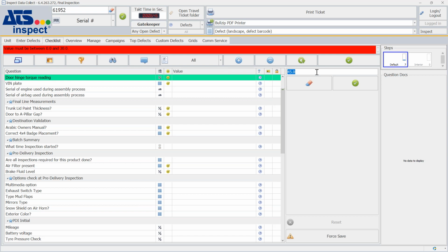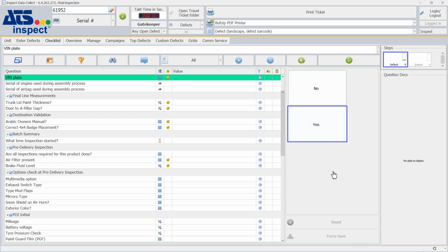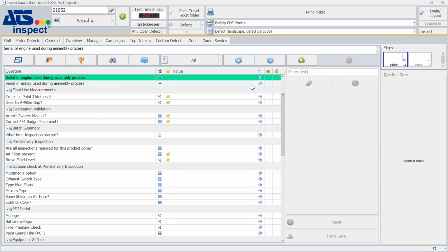And inside that reasonable limit, it will do a specification check. So let's say if I do 25, I will get a message that the torque spec is 12 to 15. So since I'm already over, I can't reduce it and I'll have to save it. If you are under, then you could actually increase the torque and fix it right away. Asking if there is a fin plate. Yes, I can do some traceability capturing here as well.